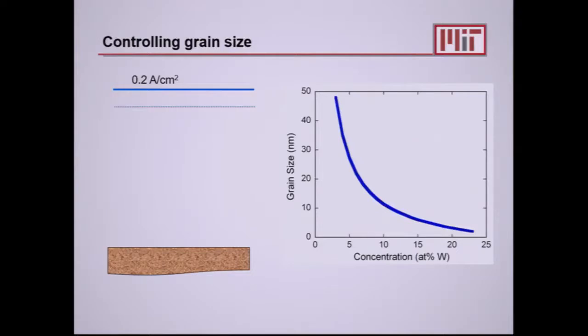And this was a very clever and inventive moment on Andy's part. And so I'm going to share with you what Andy did. I've made some cheesy schematics that illustrate it. This is the way Andy thought it through. He said, okay, look, I know I can make this one coating over here, this 21% tungsten coating, and I know exactly how to do it. I put the temperature at the right number and the pH at the right number, and I turn on the current at the right current density, and I deposit.